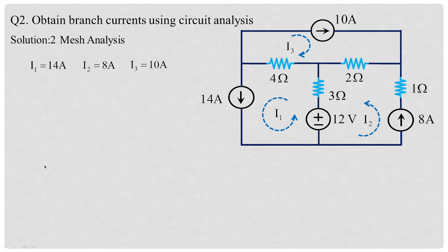So if this is true, let us apply the same logic. I4, you can see this brown arrow, is flowing through 4 ohms, which is opposite to I1 direction, opposite to I3 direction. So that's why it is minus of I1 plus I3, which is equal to minus 24 amperes. The same result we got when we employed the previous method with all the loop currents in clockwise directions.